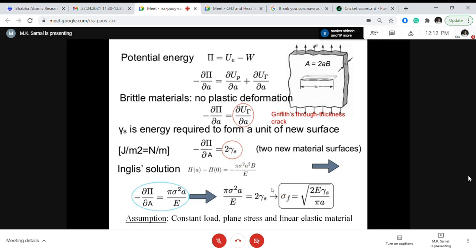So it is as if we have a longer crack, which is increased because of the plastic zone. You must have already studied this in the previous lecture; Suranjit must have told you that instead of crack length a, I will use an effective crack length, which is a plus RP. RP stands for radius of the plastic zone. So we will see then how to estimate it.